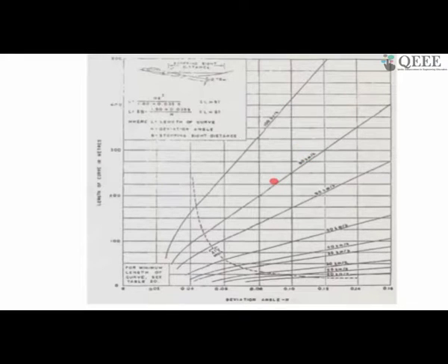But when someone is reviewing the design, they are recalculating some of the things as a proof check, they again go back to this basic understanding, and from this basic understanding they calculate the radius, they look into the side distance, they look into other details for that. The extra widening can also be done by the software, but you have to tell the software that you provide the extra widening using certain formula, certain guidelines. You also have to tell the software how many lengths you are going to provide and so forth.